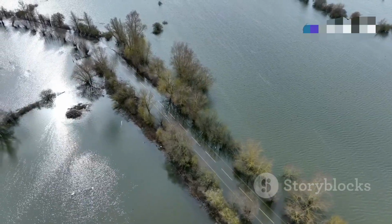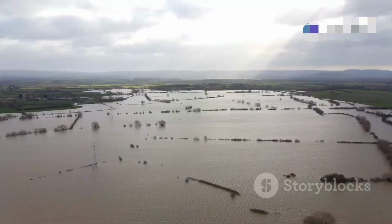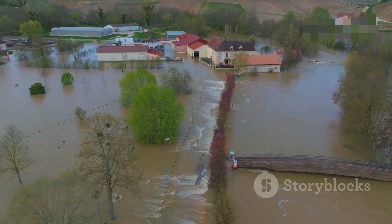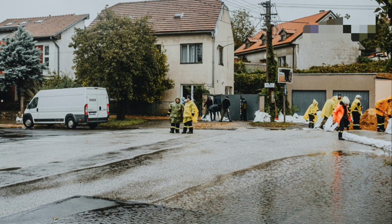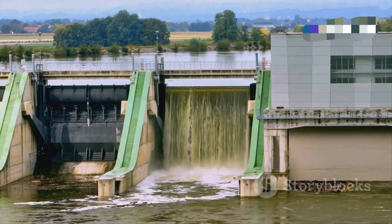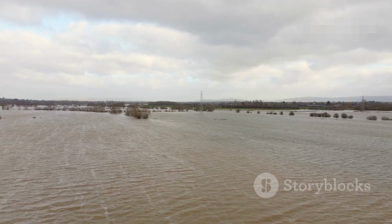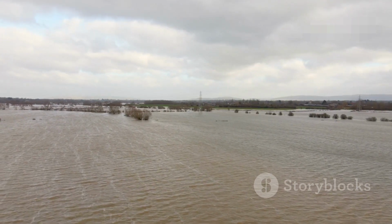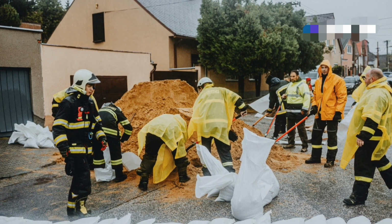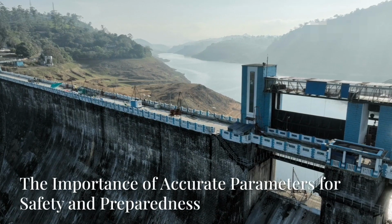The differences in flood waves generated by various breach scenarios have direct implications for downstream inundation. A higher peak flow will generally lead to deeper and more extensive flooding. The timing of the flood wave is also critical. Faster developing breaches result in less warning time for downstream communities. HEC-RAS modeling allows engineers to quantify these differences. By comparing the inundation maps and flood arrival times for different scenarios, emergency managers can better understand the range of potential impacts. This helps in developing more comprehensive and adaptable emergency action plans that can address various contingencies effectively.